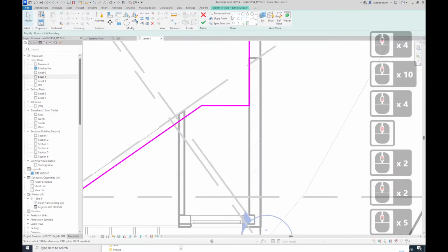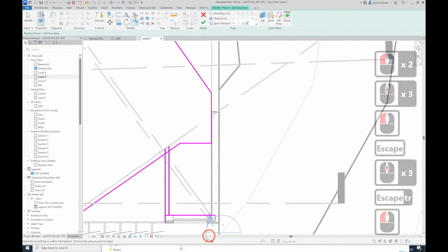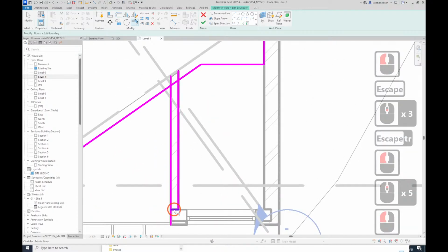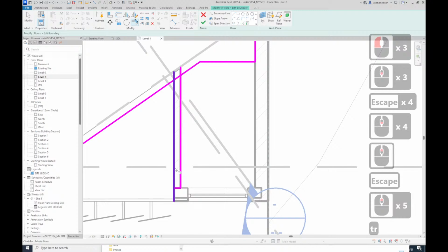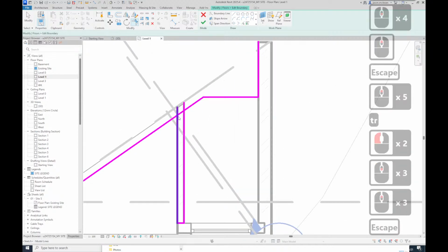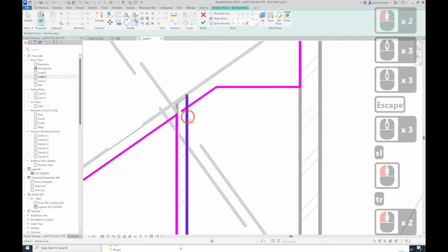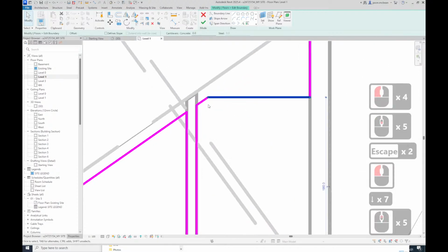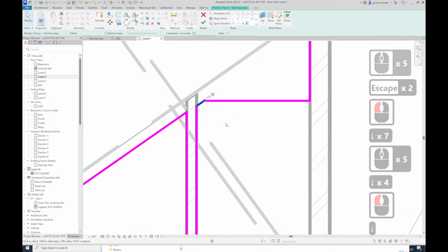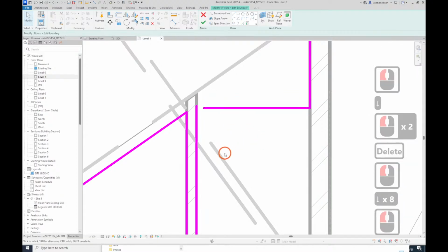Is this an opening? Yeah. So maybe it'll do something like that. But this can just be a wall from below. Trim, but watch this. Technically, if you wanted to do that, and then this you can just nudge up. Revit just doesn't like elements that are zeros, so you might have to delete and then trim this guy.